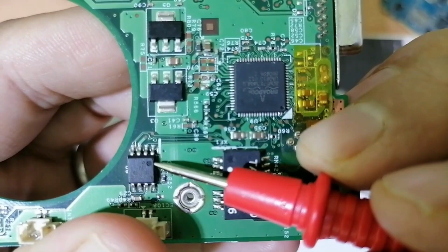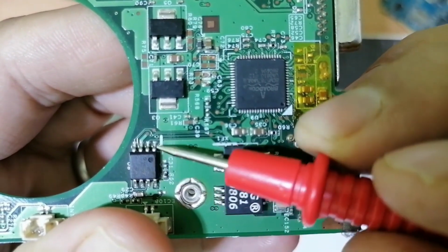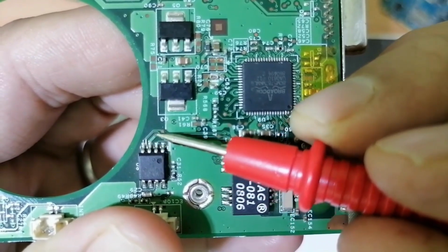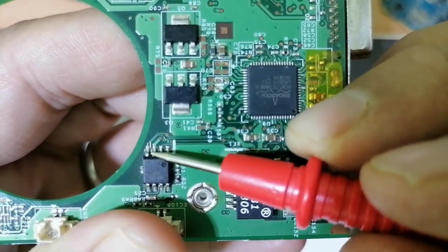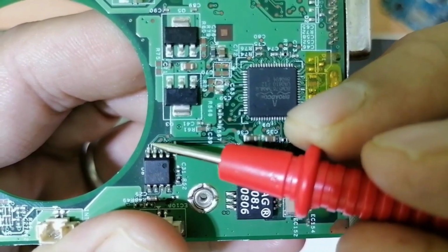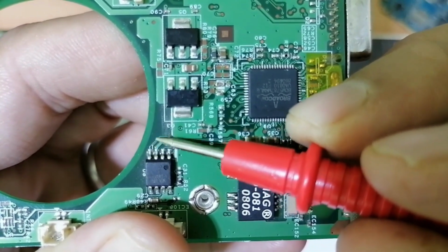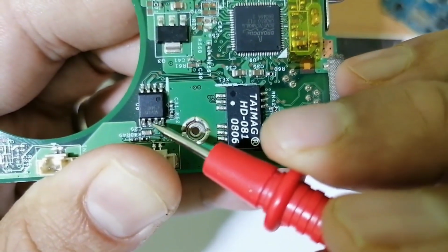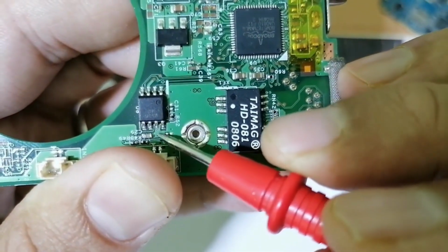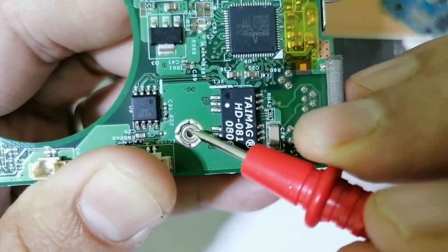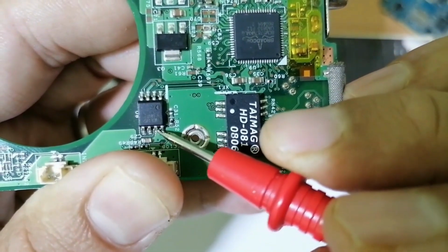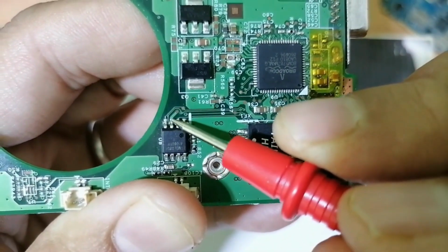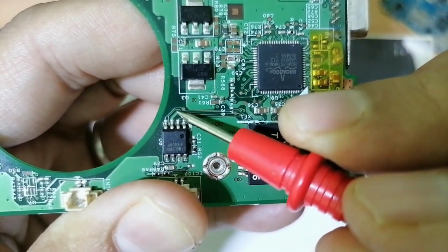So here I have another example. Do you see? This is basically an IC, not a MOSFET. Here we have pin 10. Do you see a bolded line? It means this is the input power. It could be 5 volt. And over here we have, as you can see, 10 pins. If we go here, we also have a control signal, and we have this bolded part connected to this hole, which means this is the ground. This pin is for ground. This pin is for input voltage, for VCC. Why? Because we have the bolded line here.